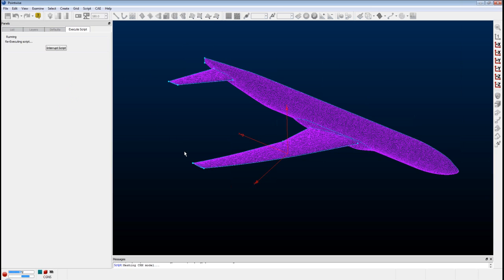And those of you familiar with Pointwise know that if you select a model and apply the surface mesh to the model, each quilt within the model gets its own domain. And this is some key information that we're going to need when we actually begin refining the mesh.